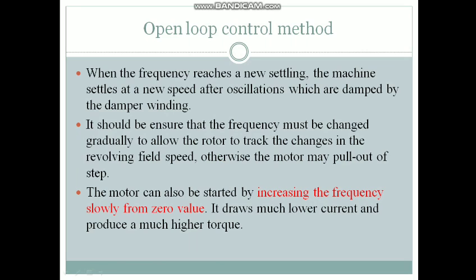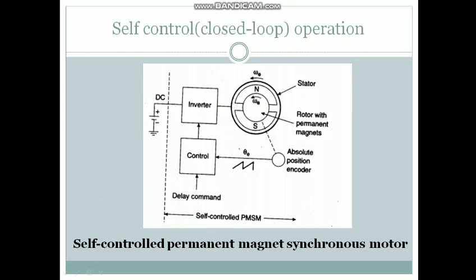The motor can also be started by increasing the frequency slowly from zero. It will take a much lower current, and it will also have a very high torque.